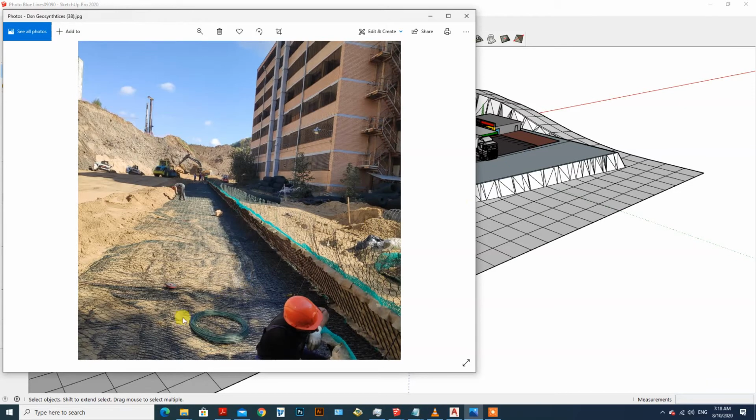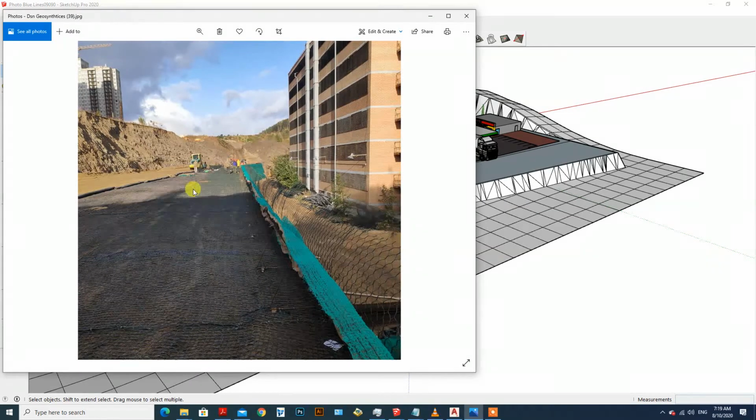You see, it comes with this tail that goes into the fill, and then we backfill, we compact all the fill in layers. But the fill type that goes closer to this slope here has to be something with organic matter that allows the grass to grow. So basically, as you can see, they've just lined them up. So we could probably consider using it, to see how it actually looks with a tail that goes into the fill that makes it stable.